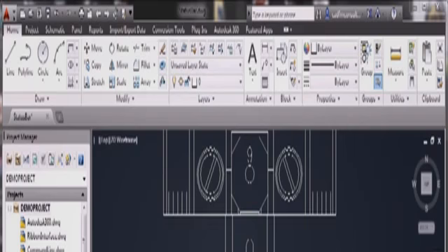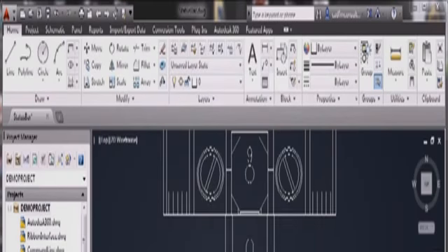There's another setting for these drafting settings that I'll show you in a moment that will make your life a lot easier. I'll switch object snap on. There's my drafting settings. It prompts me which object snaps do I want to switch on. So I'll switch on endpoint, midpoint, and center, and also intersection and extension. Now I will cover these object snaps in more detail later on in the course, so don't worry too much about them right now. Endpoint is the one I actually need, but I'll OK those that I've switched on.